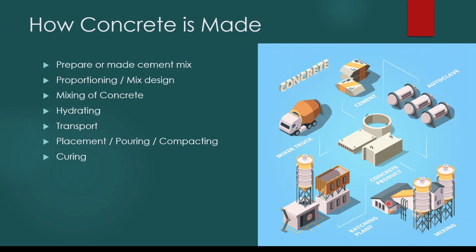If I come back to the testing, the cube testing may not be done for all the trucks that come to the site, but it depends on the criteria you specified. It may depend on the magnitude and the scale of the concrete. Likewise, there are many things to consider. Anyway, we have to do the testing of the concrete before pouring. So you may refer to the guideline on how we do the testing.